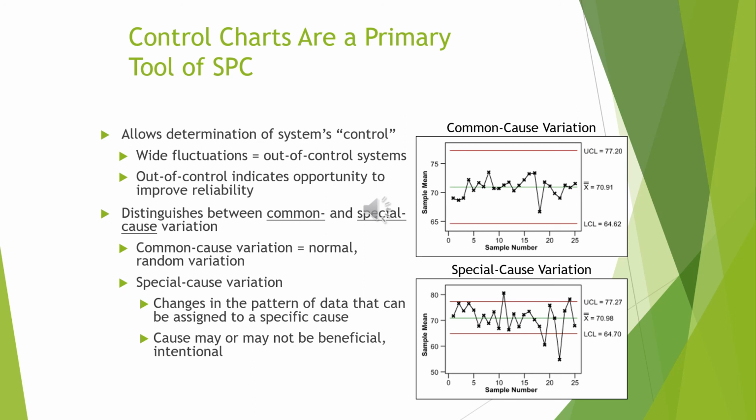By in control, we mean it's not varying more than plus or minus 3 standard deviations, or doing some other funny things, right? So what they do is they make these charts, and these charts tell us a lot. There are two types of variation. There's the common variation, which is basically just random variation. And then you've got special cause variation. Special cause is where you can find a specific cause for the data. So you can go into the process and say, oh, this is what's causing it to vary so much, or this is what causes one point to be out of control.